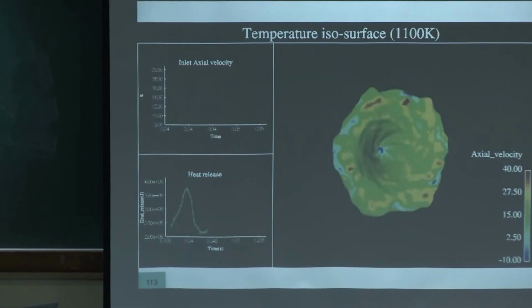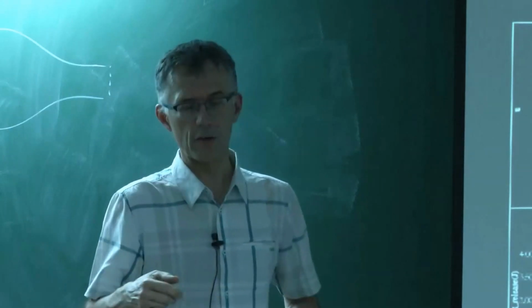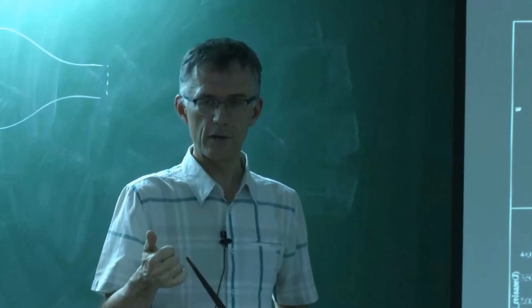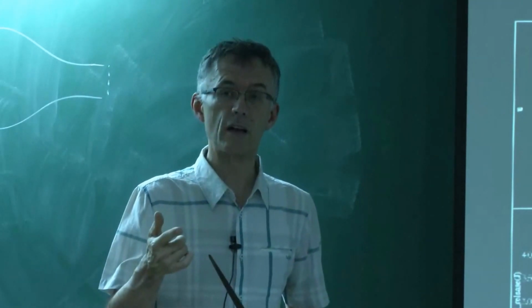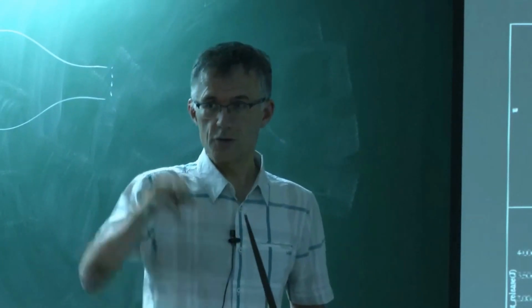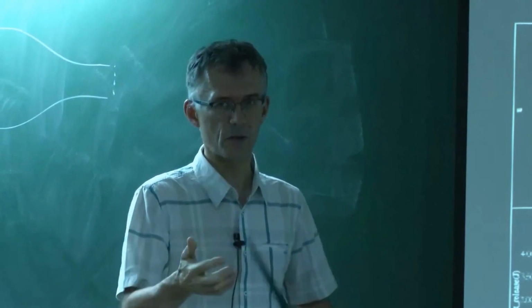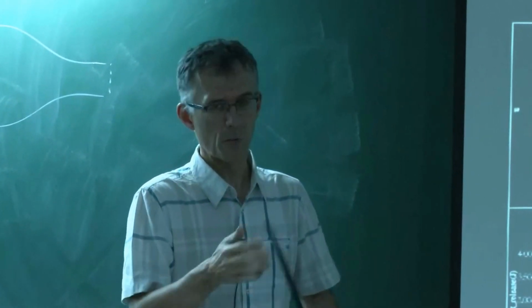So how do we decide upon the kind of signal to be sent to the inlet? Usually you have many options. You can use a sinusoidal wave. You can use many sinusoidal waves at the same time if you want to save money. You can use an impulse function, or you can use white noise, and then you use Wiener-Hopf methodologies to extract the flame transfer function. But the principle is always the same.